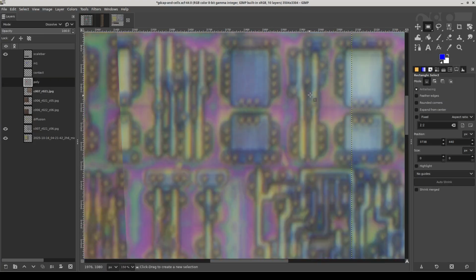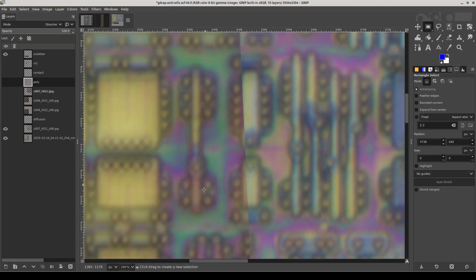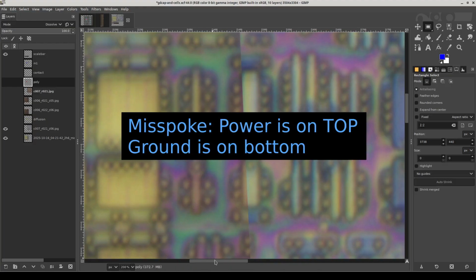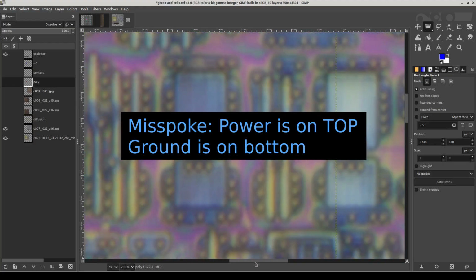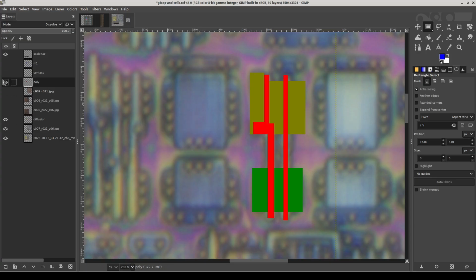And now we're going to shift gears to this cell right here. It's a little bit more complicated than the inverter we were just looking at. It's got 4 transistors. We can see there's 2 up top, there's 2 at the bottom. And looking at some of the other cells in this row, we can see another of the same inverter we just looked at. So the NFET is here, the PFET is here. So that means that the power rail is on the bottom and we are in the canonically right side up orientation.